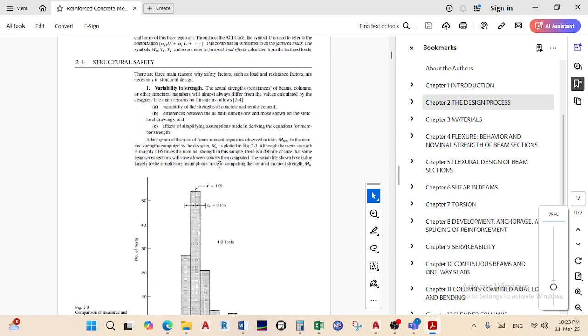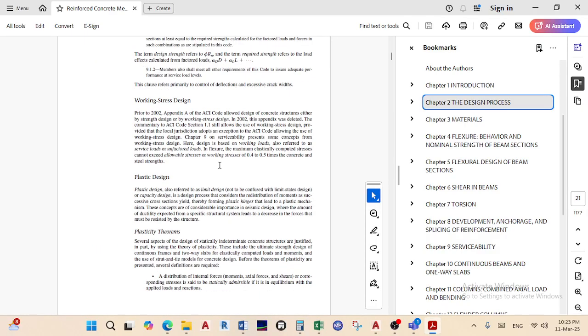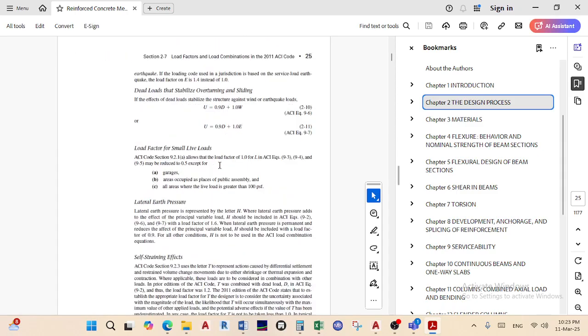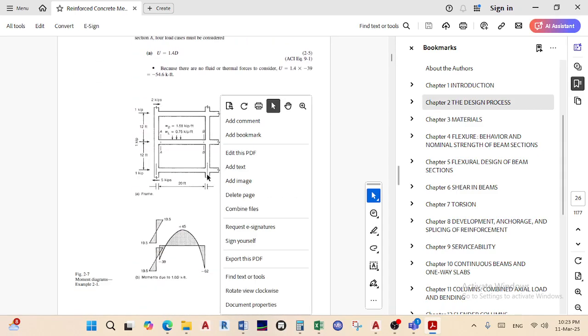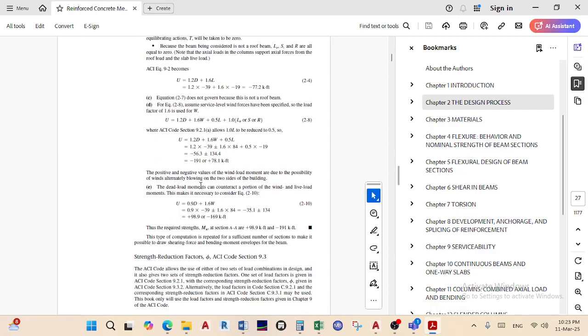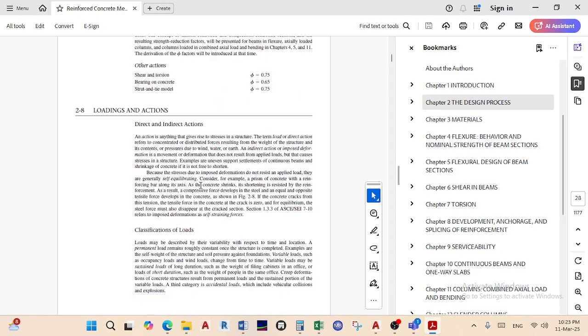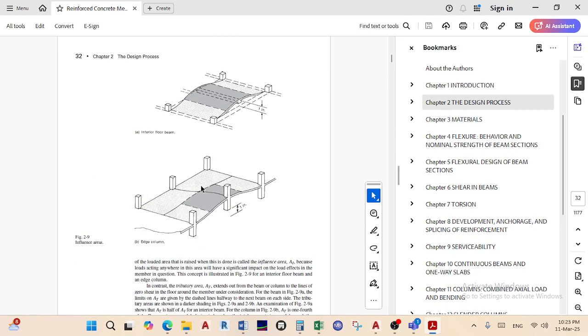So that's the mathematics that's happening there. The ideal way of designing is you have to apply reinforcement in a way that is personalized to the actual member or actual column. But in our case, we just used one, copied, and pasted everywhere else. That's why we're having different utilization ratios, even over the same steel of reinforcement applied.